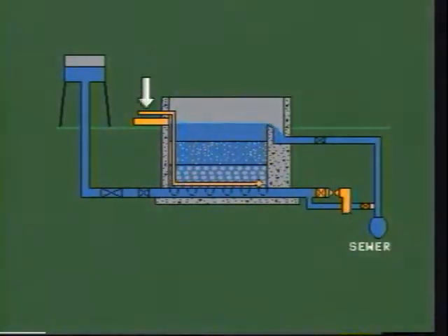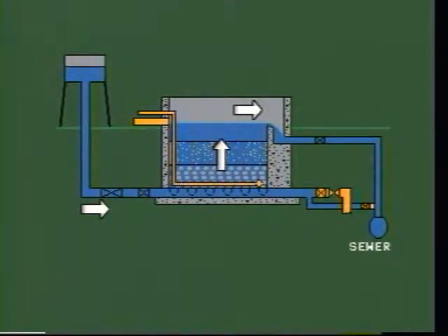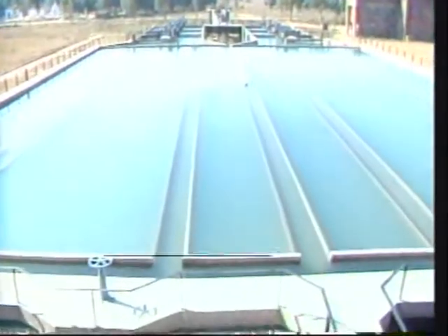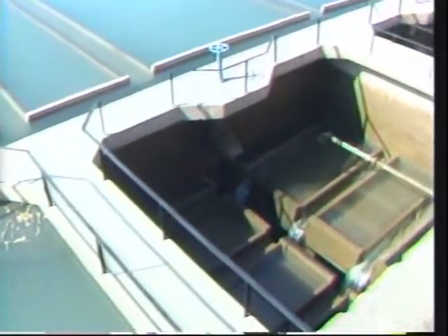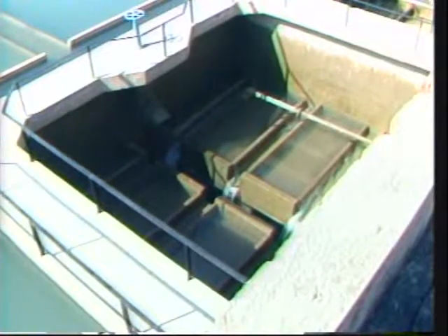The graphic illustrates the process of backwashing. Compressed air is made to pass through the filter beds from bottom upwards. Thereafter, water enters under pressure from the bottom upwards and cleans the filter beds. The process of backwashing should be continued till all the impurities flow out.